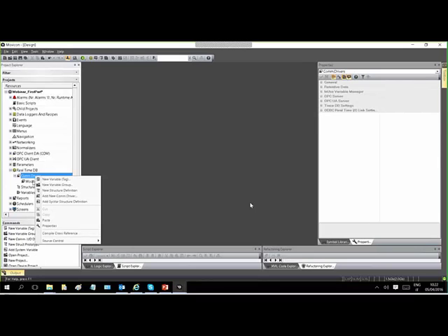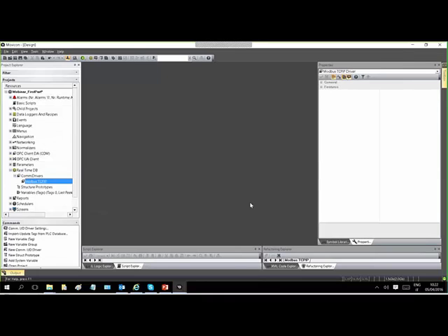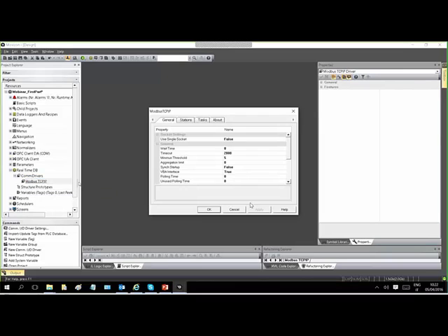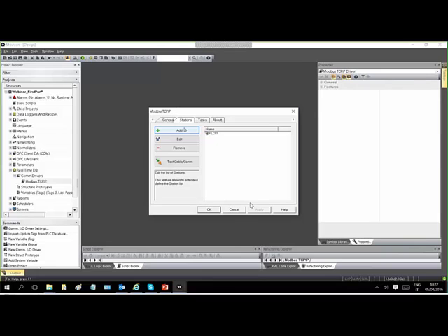A project could be with one driver or multi-driver. There is no technical limitation about this. So you can add a Siemens driver to interconnect the main controller, a Modbus driver to connect additional SCADA, and enable in parallel an OPC communication and connect an OPC server. So there are no limitations.